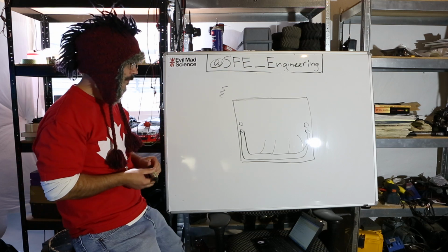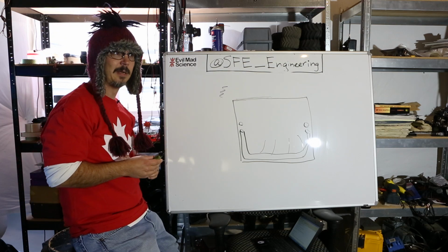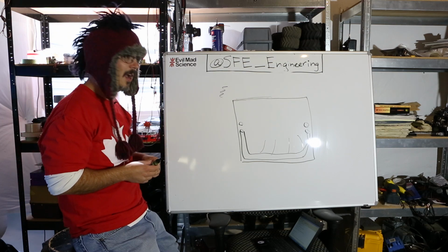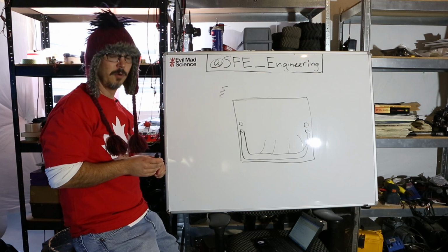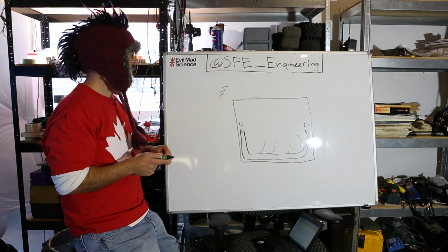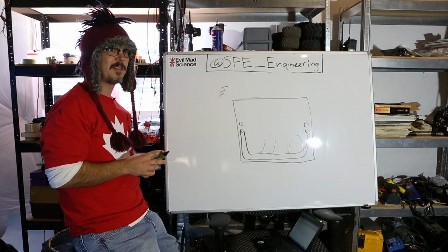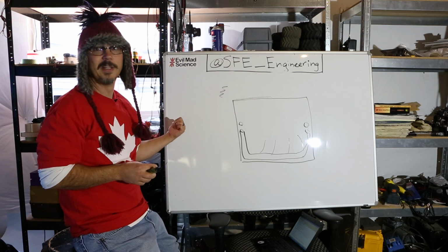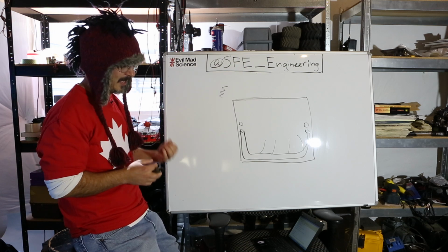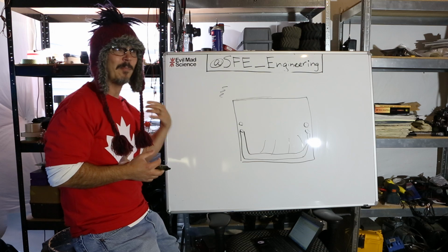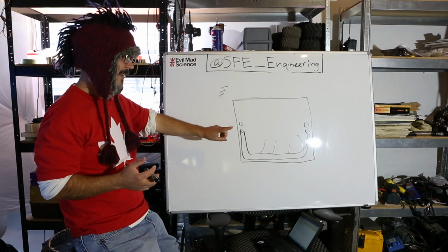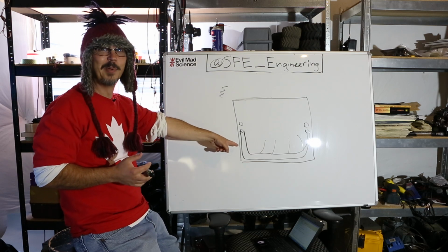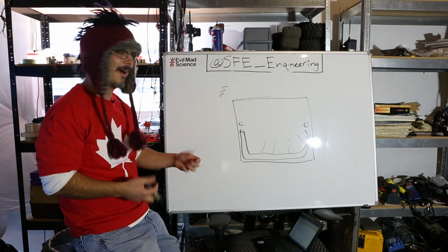Most of the time, if I'm making big traces on a PCB, I keep them as short and to the point as possible. Big current paths, I want to get off the PCB as quickly as I can, right? I trust a big, thick gauge piece of wire to carry more current than a big piece of wide copper. I want a wire. I don't want that.